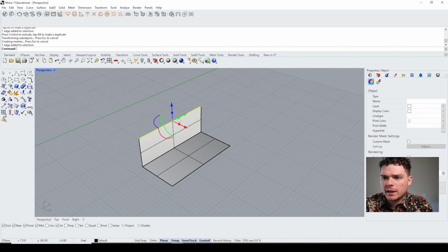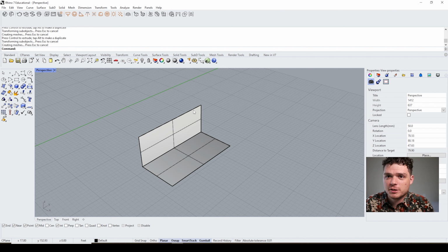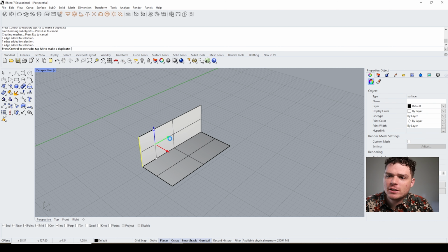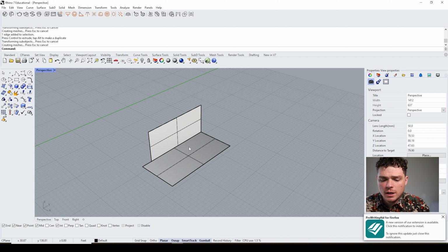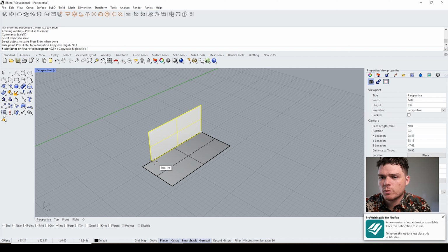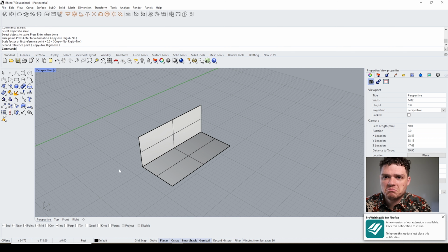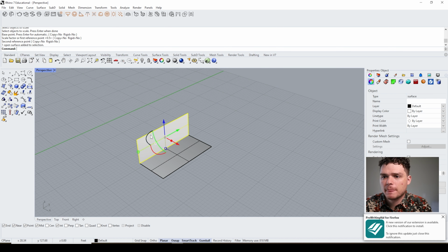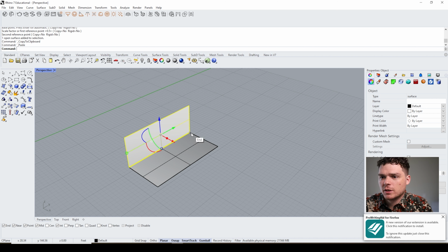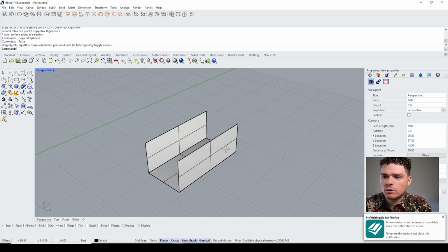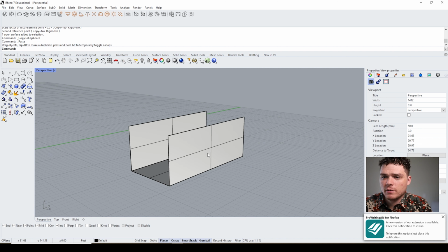Again, using this SketchUp, what I call a SketchUp technique, at some point we just need to call it the Rhino technique, which is using this Control Shift, you can select the line work, and that just allows you to move these edges really easily. Another thing you can do is hit the scale 1D. I use this all the time as well, and you can move things around that way as well. So we have, very quickly, Control C, Control V, we almost have a house here.